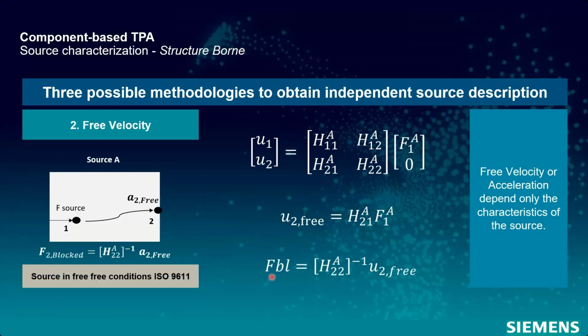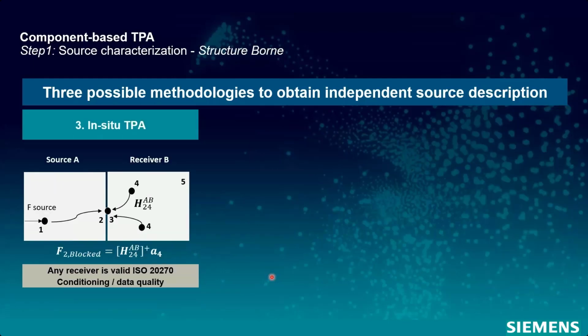You just have to make sure that the stiffness of your source is 10 dB more stiff than your receiver, so that it's approximately this free condition. You put accelerometers on your connections and you can capture the free velocity or free acceleration. Of course, for a lot of applications, it's not possible to create test rigs that accommodate that, that are very rigid or very soft.